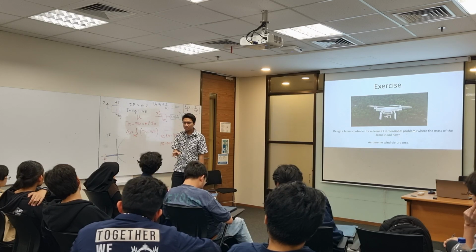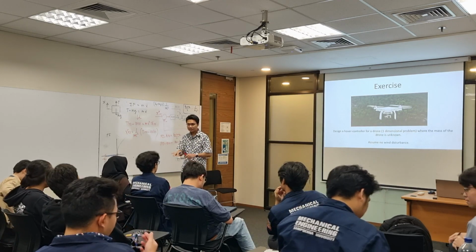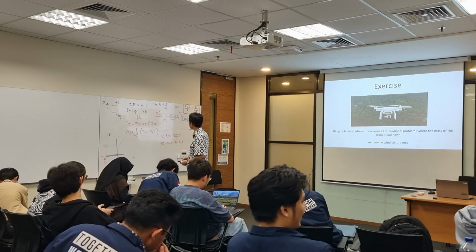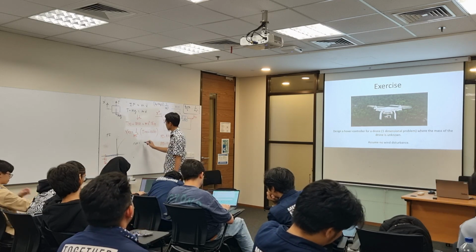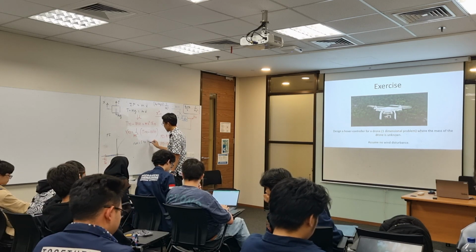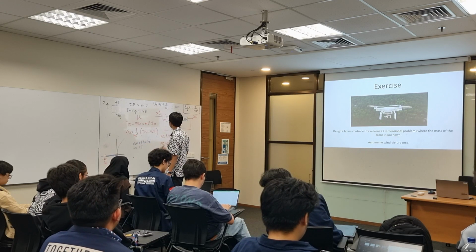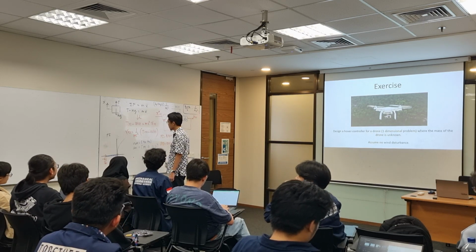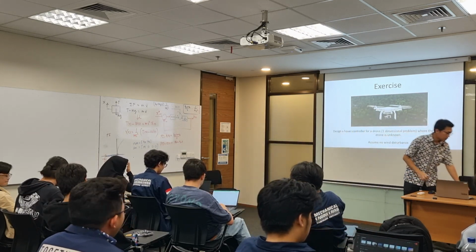You want to try using MATLAB? Go into your MATLAB now. You write down the numerator is KP and then KI. The denominator is M and then 0, 0, 0.